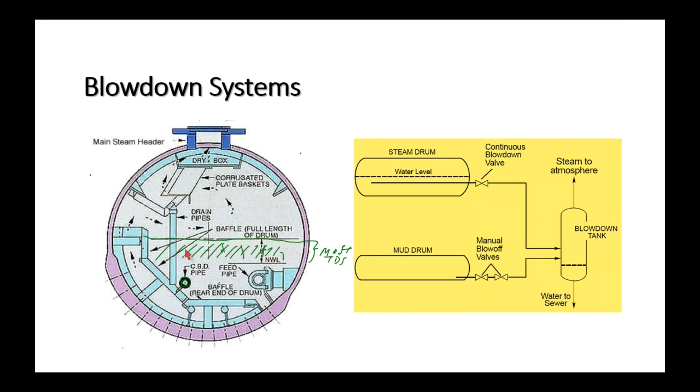He would lower or raise the water level set point in the boiler so that he knew he was maximizing the dissolved solids concentration being discharged, and that way he could discharge less water and chemical and discharge more of the dissolved solids. So he was a little bit wacky, but he was a very good engineer, I tell you.